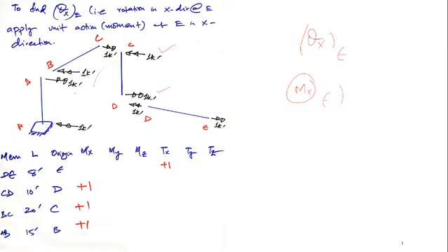In terms of moment, you should know that this is clockwise and this is counterclockwise. I've been telling again and again that these are my directions, and this is from the right hand rule. These are all counterclockwise. This is my x, this is my y, this is my z. Okay, this 1 kip foot is counterclockwise, I have balanced with clockwise. Again joint B is balanced, and finally it has been balanced. So it's very easy.